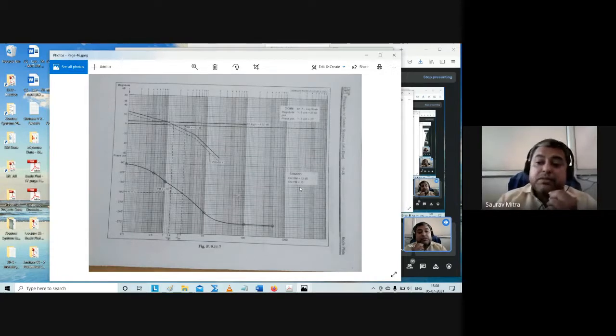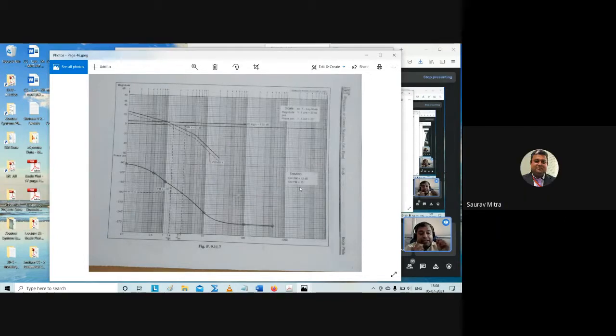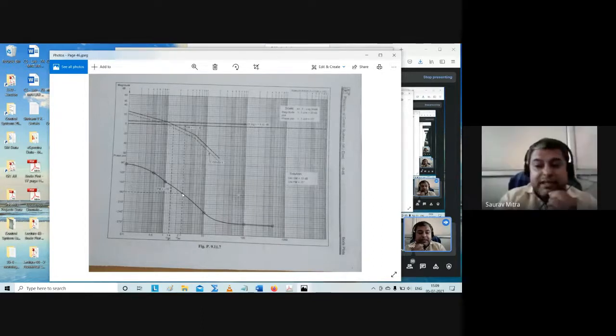Next you are supposed to find gain margin. For gain margin, you are supposed to find the phase crossover frequency. That means the frequency at which the phase is crossing the minus 180-degree line. Okay, so this will come through drawing only. So you will be finding the phase at 1, then you will be finding the phase at 10, and then if you join them, you are going to get this trend. So from 1 and 10, if you join, you will find that it is crossing the minus 180-degree line at 2.7 radian per second.